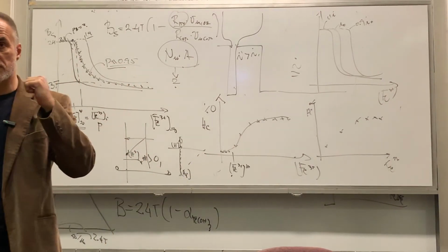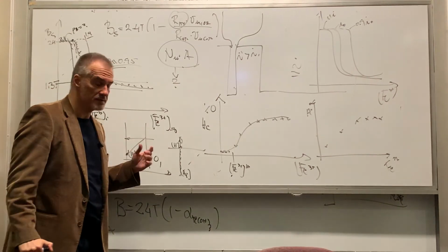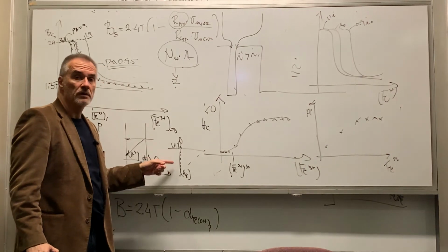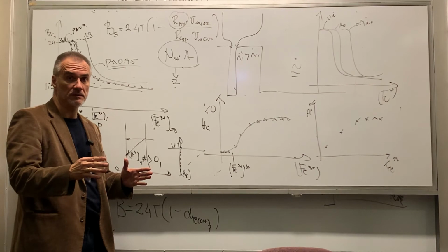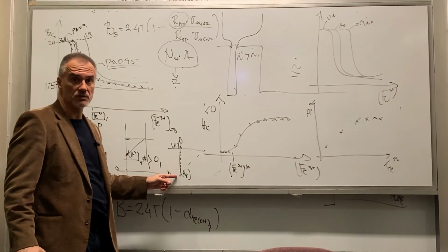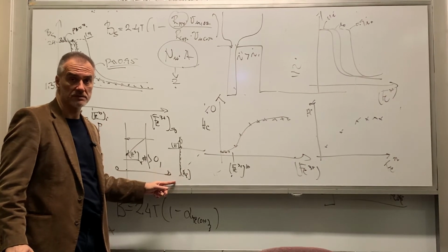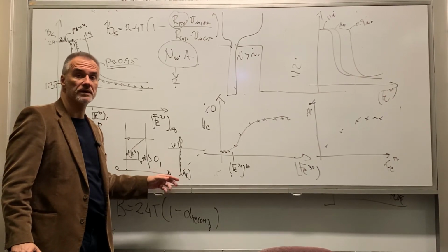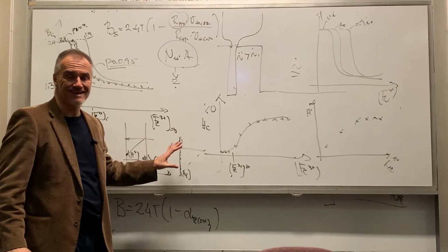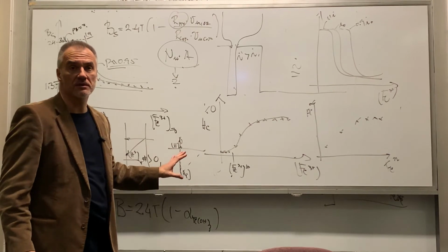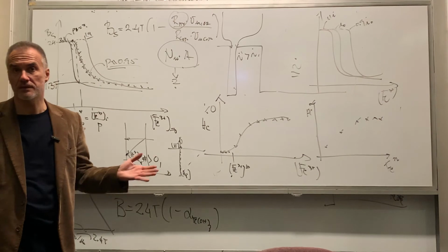And we have these equations for the unsteady state and so on. So the thing is also that you can calculate how long your pulse current should last before you encounter a situation where the interfacial concentration of hydrogen plus is lower than allowed for precipitation of nickel hydroxide. And that can serve as a parameter for your pulse deposition cycle calculation, basically.